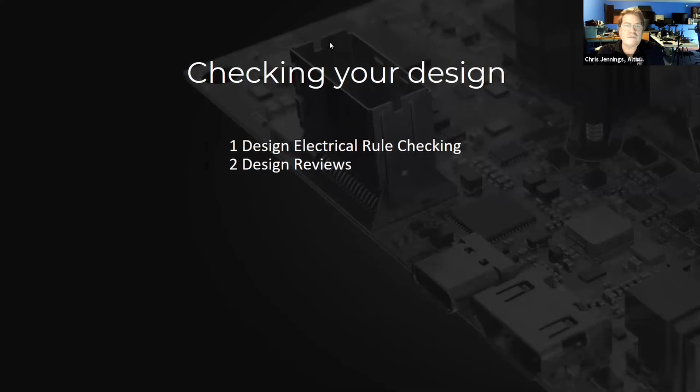One of the things that I ran into with a design 7 months ago was I used a very unique part. Like nobody else in the world made it, because it was exactly what I needed. And then I couldn't find it because they decided to stop making it. It's a voltage controlled amplifier, in case anyone was wondering, for my analog synthesizer project, essentially. I have since found another alternate source. The problem is it's a completely different pinout, so I have to redo the board if I want to continue making it.